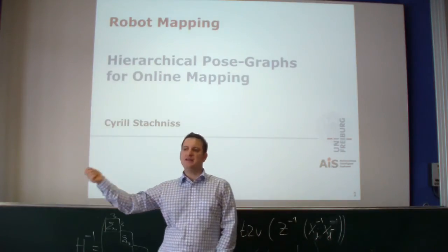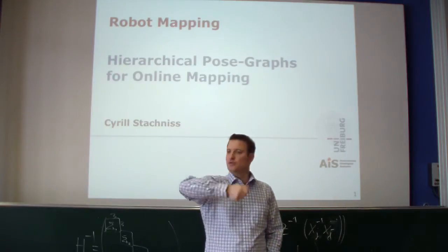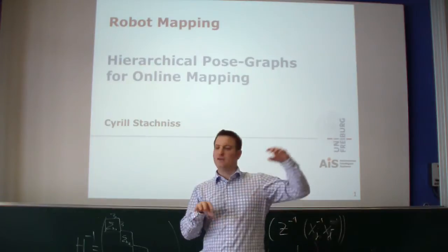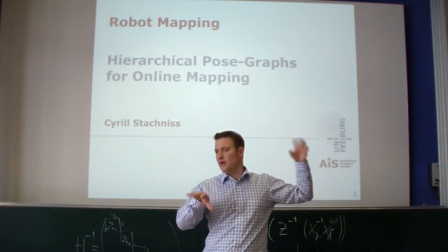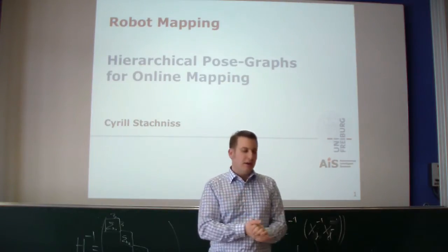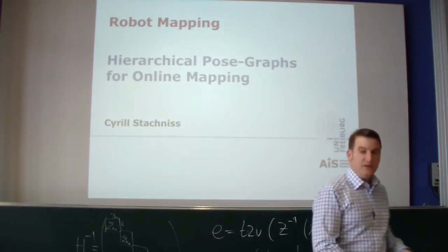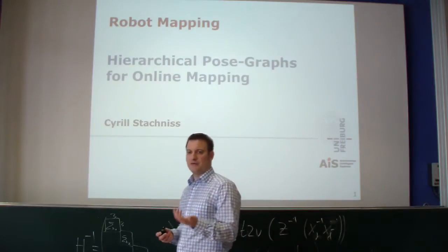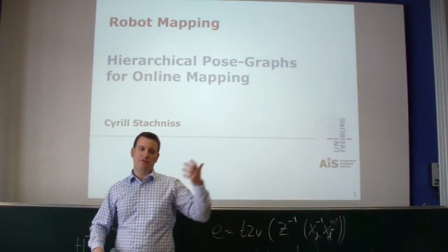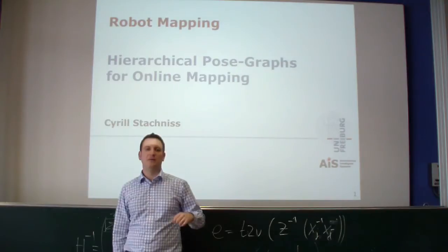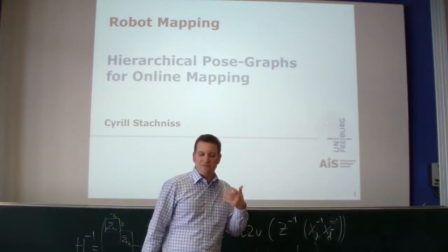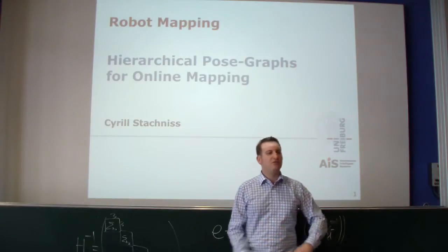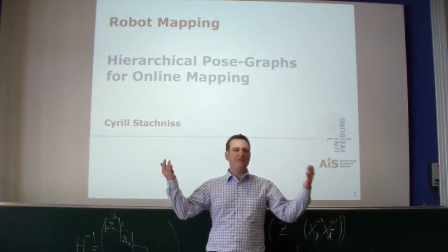That means adding this observation to my graph by, for example, saying the current pose is related to a pose we have been at previously with this relative transformation. In order to do that, we need to have a good, or at least a reasonable, estimate of the configuration of the graph, because if the configuration of the graph is completely messed up, the only way I can actually check for those correspondences is to revisit all nodes and see, for example, if both